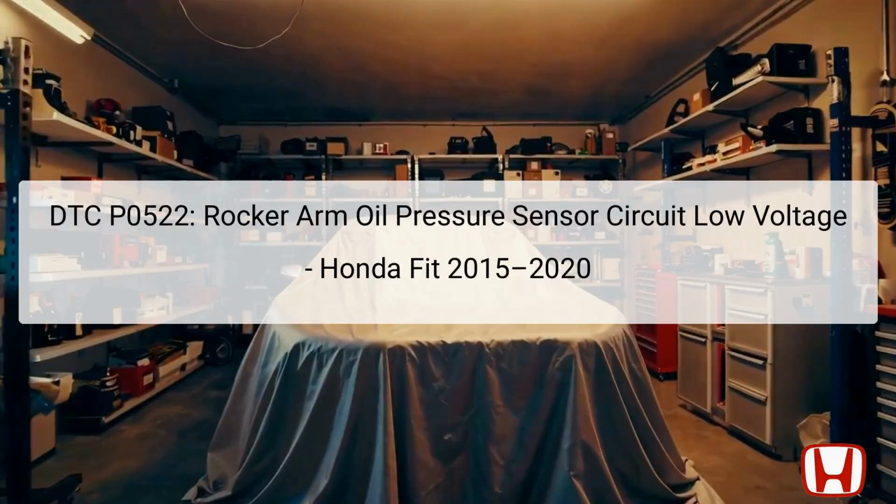DTC P0522 refers to a malfunction in the rocker arm oil pressure sensor circuit, indicating low voltage in this critical component. The rocker arm oil pressure sensor plays a crucial role in measuring the oil pressure, delivering lubrication to the rocker arms in the engine. Proper oil pressure is essential for optimum engine performance, preventing excessive wear and tear.